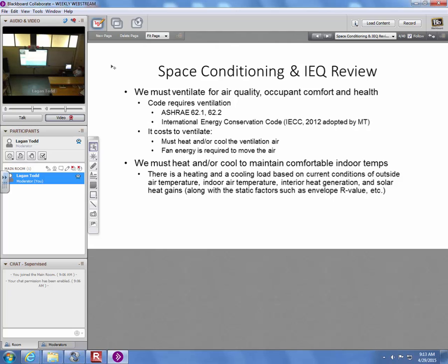The temperature differential between the temperature at which we like to maintain our indoor environment, say 70 to 74 degrees, and what temperatures might be seen in the outside air, the ambient condition, that's a very large temperature differential that we have to overcome with HVAC, with heating. So it's a lot of energy, potentially.